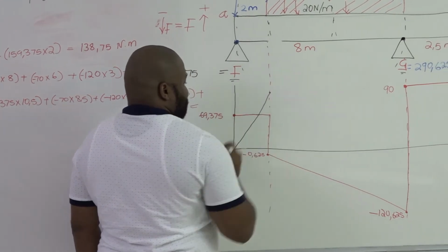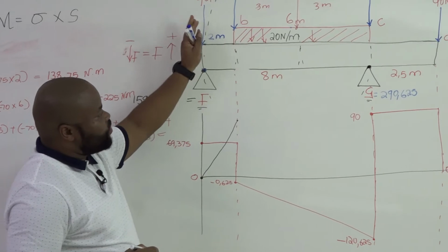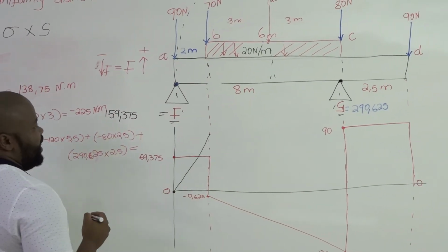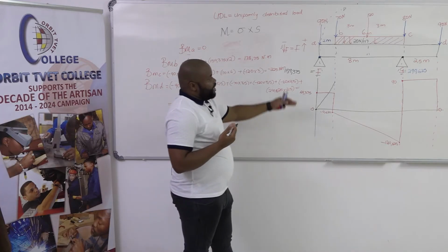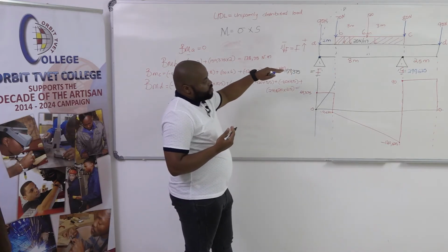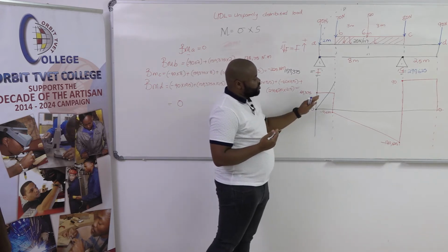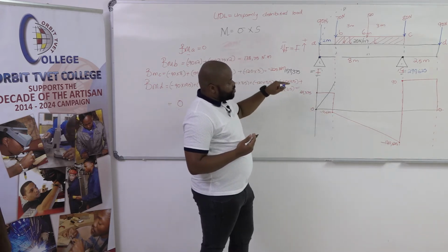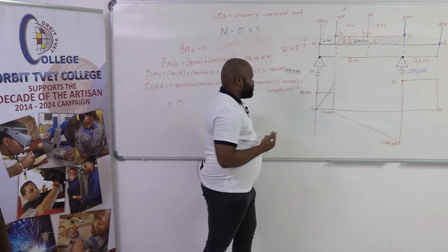It's going in a slope direction because between the forces we don't have a UDL. You will see as it changes when we are dealing with a UDL that is on top of our beam. The shape changes. We are no longer going to slope, but we're going to go down in a parabolic form.